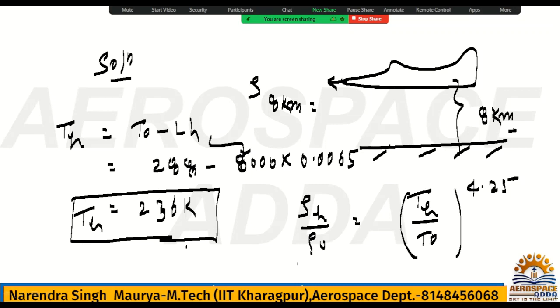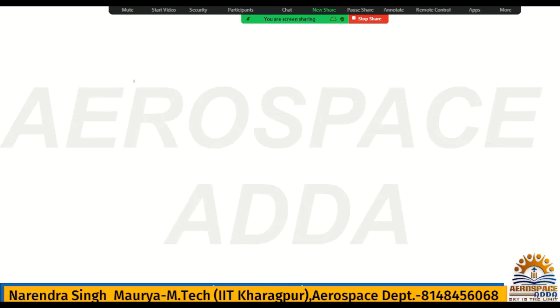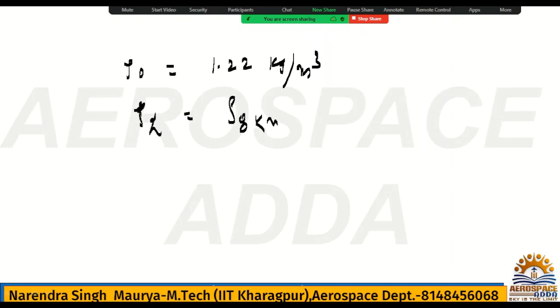What is the rho naught? Rho naught is the sea level density, 1.22 kg per meter cube. So what is the rho H, which is nothing but rho at 8 kilometer? It is nothing but rho naught into TH by T naught to the power 4.25. Yes or no?